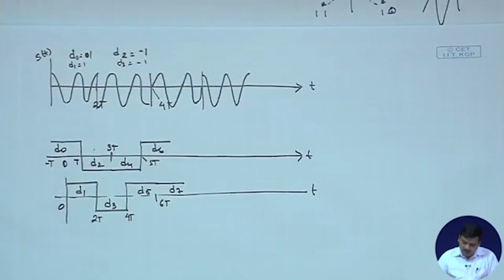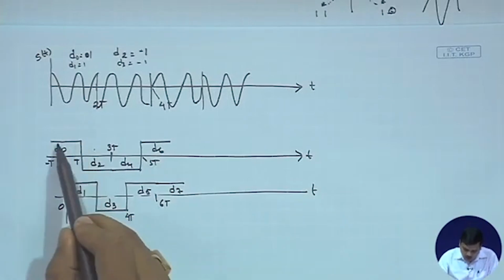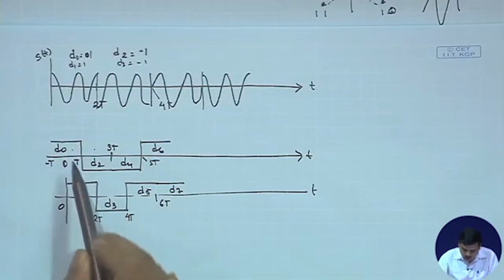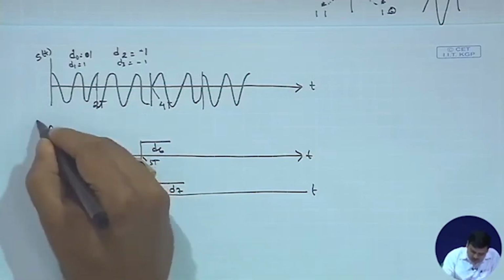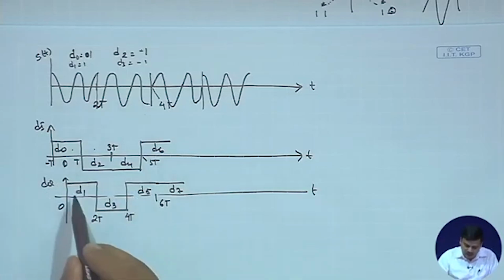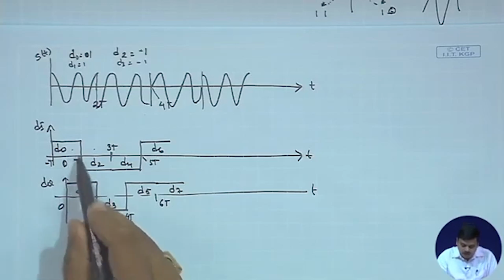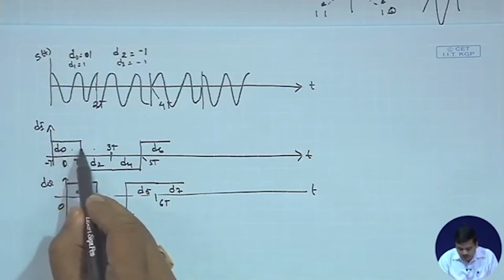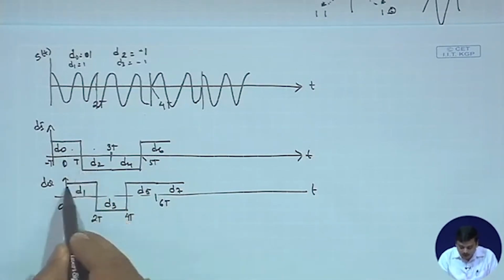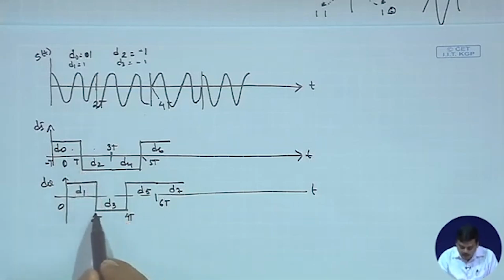So, if you see this, what is happening is that only one of these two channels, this is the I channel and this is the Q channel, is changing at interval of t. Not both of them change simultaneously. So, when the even changes, the odd continues to remain in the same phase, and here we have a similar situation.